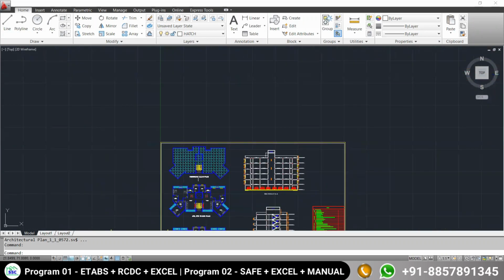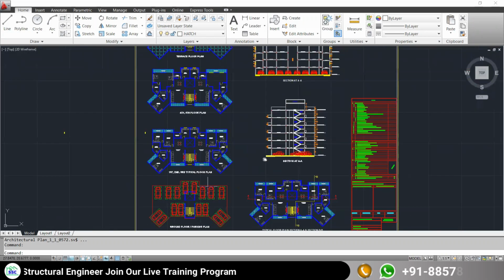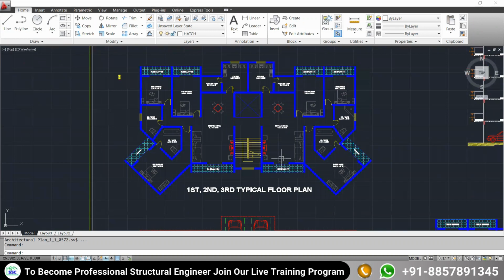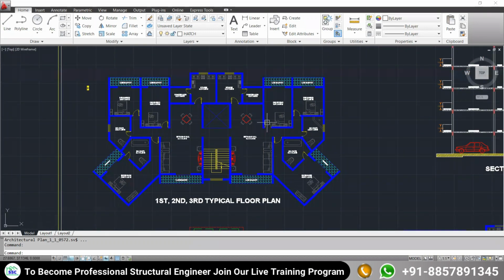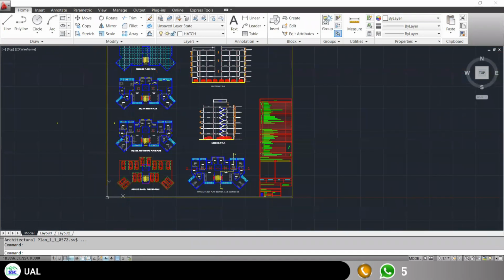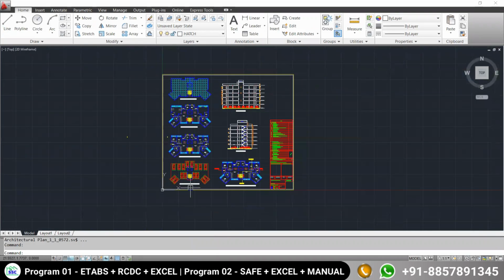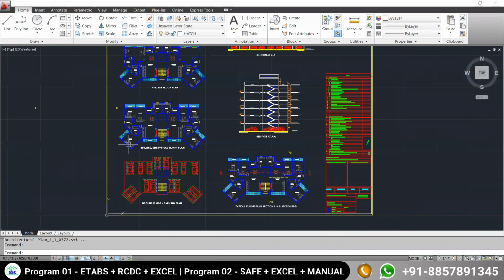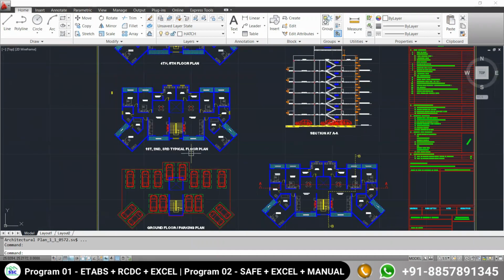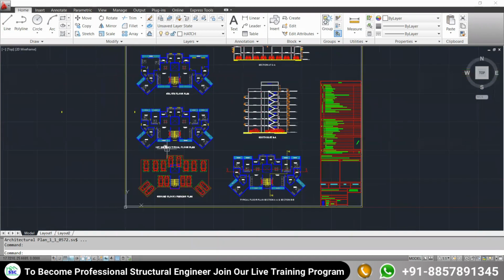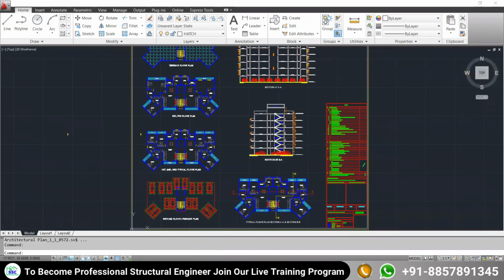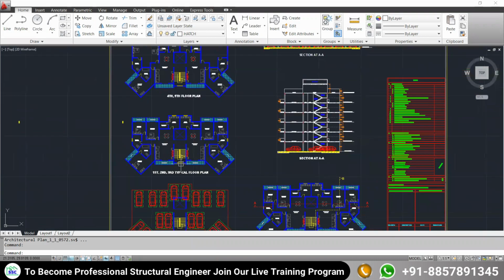At any one floor, you first have to put your column and decide the positioning. Over only one floor you put the column, and later you have to check that position at all upper and lower floors, to ensure that the column is not going to create any kind of obstruction in your building at any floor. So here the problem is what? Amongst all these different floors, you have to decide on which particular floor you put your column first.